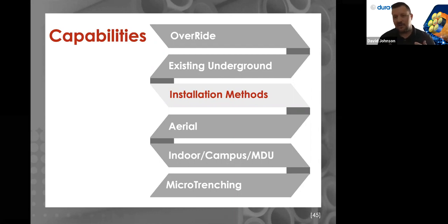And really it's the method. The method is what allows it to avoid tangling as much as possible. But the answer to that is you can't completely avoid it. And there are times where those microducts just might stop. The great thing about that is our microducts they have footage markers on them. So when that does happen, we know how far we've gone in, we can walk off, and we end up having to dig up that particular location to find out what happened. Maybe it's a conduit, existing conduit system. Maybe it did get tangled. But that is how we work through it. But more often than not, it is successful.